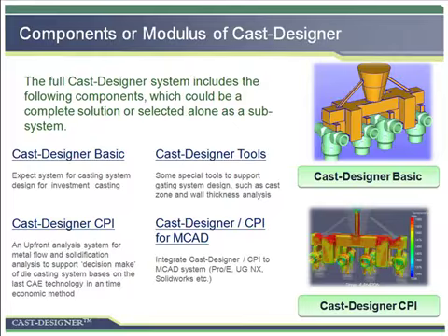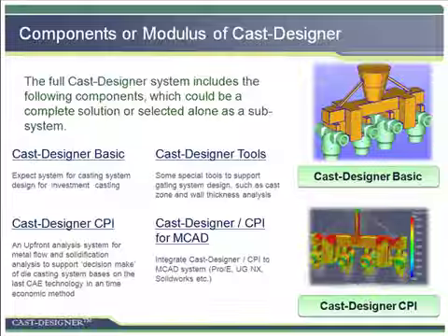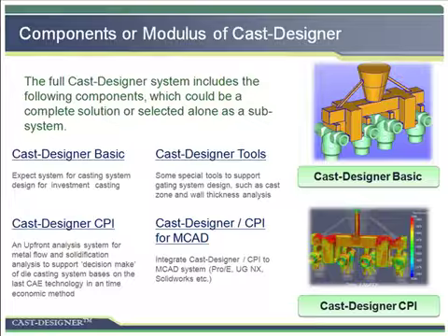The third one is Cast Designer Tools. Some special tools to support casting system design, such as cast zone and wall thickness analysis. It is optional. There are also other modules, Cast Designer for MCAD, and Cast Designer CPI for MCAD. These modules allow integrating Cast Designer and Cast Designer CPI into an MCAD system. The supported systems include Pro Engineer of PTC, Unigraphics NX of Siemens, and SolidWorks of Dassault Systemes.